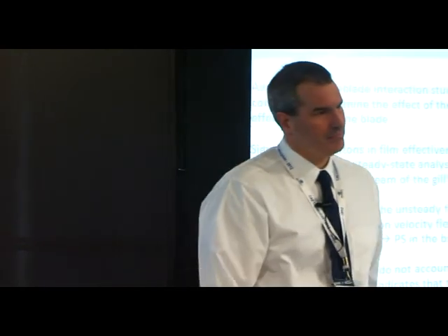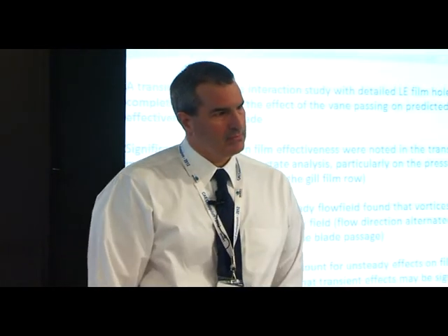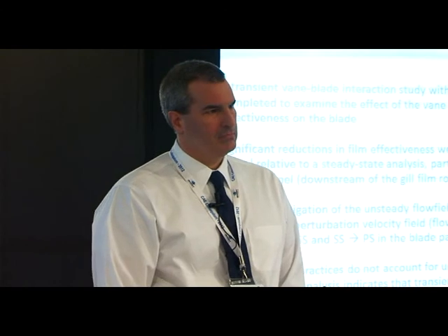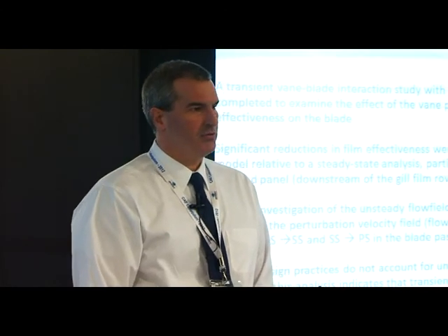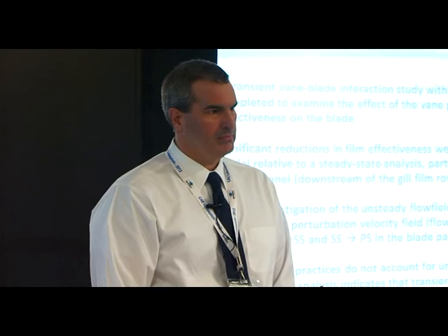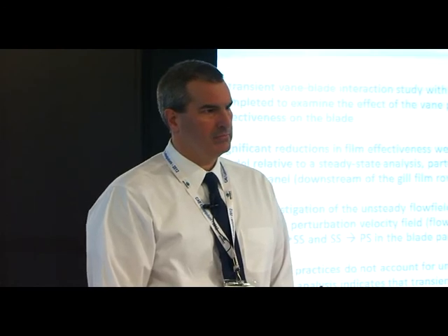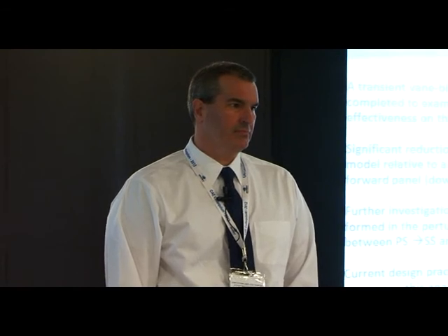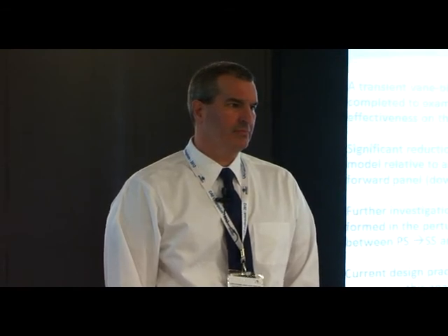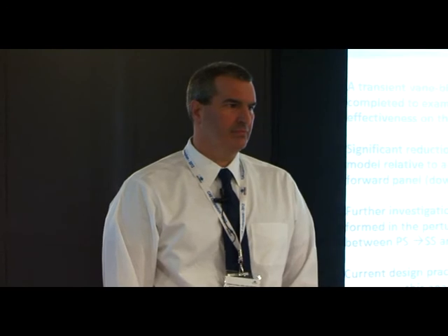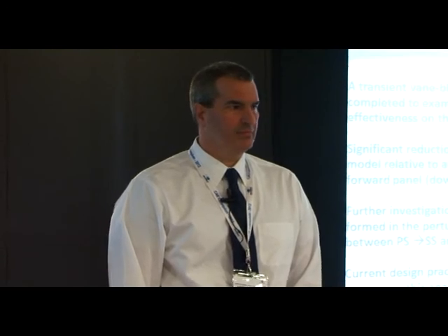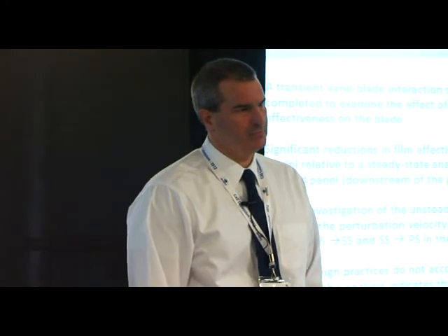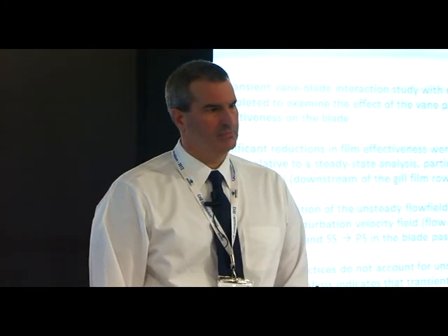And one more thing, the number of grid cells you have used is about 2.5 million cells. It was about 10 million total for that. Yeah, 10 million. That means you are effectively solving a direct numerical simulation, so why do you need a turbulence model over there? If you had improved the time step accuracy, with that kind of grid, a DNS or LES simulation would give a better approximation compared to the turbulence model you are using.